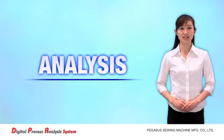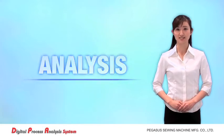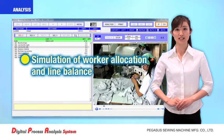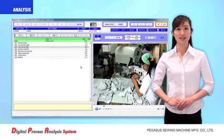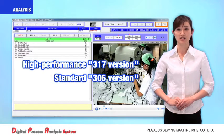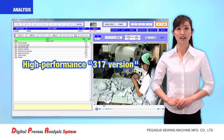What follows is an explanation of further utilization of the DPA system with the analysis function. The analysis function is a simulation of the production line's worker allocation and line balance based on the operation time data produced from the standard video. In the high-performance type 317 version of the DPA system, these simulations can be calculated automatically. And in the basic type 306 version, the simulations are done manually. Here, we will explain using the high-performance type 317 version.